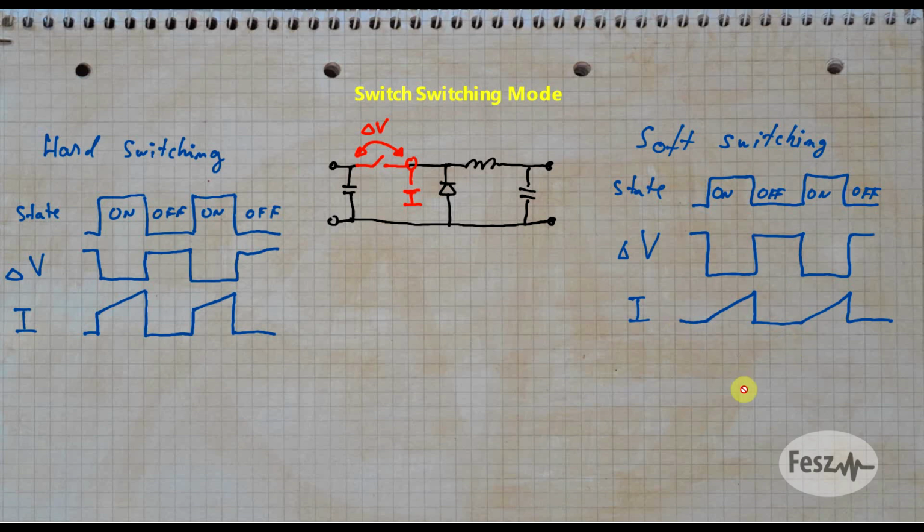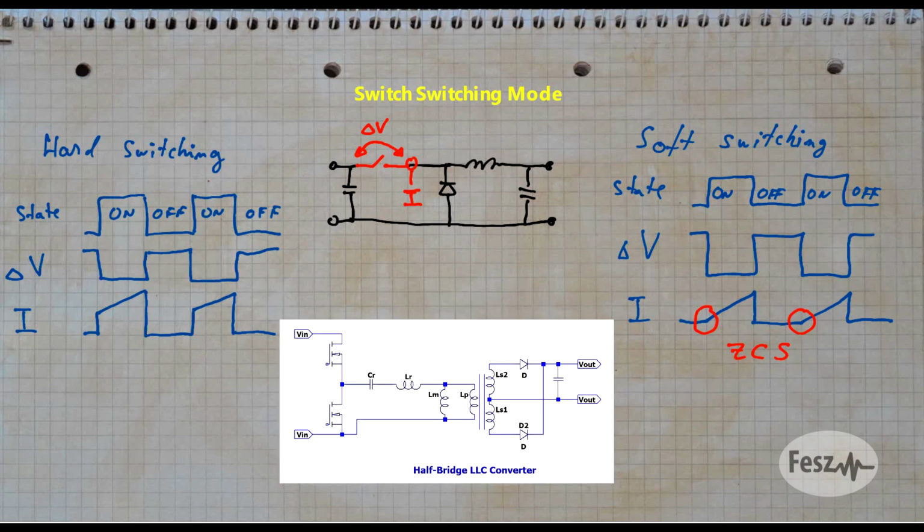So in the soft switching category, we can have special control schemes that keep the converter in some form of boundary conduction mode, so this can be applied to almost all topologies. In this example, both waveforms can be applied to the generic buck converter, with the main difference that on the right side, with soft switching, we have zero current switching during the turning on phase, but you also have dedicated resonant topologies where the power stage is driven with a switching frequency equal to its self-resonance. An example of this being the LLC converter.